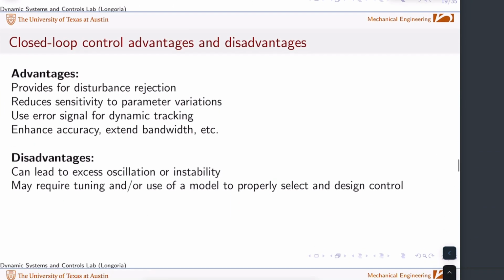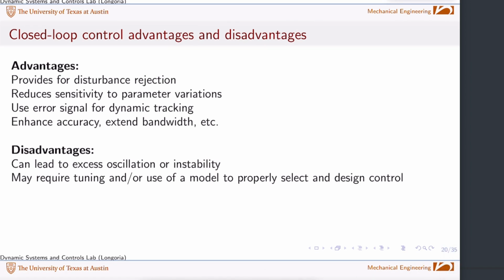It is good to discuss why we close the loop as opposed to open loop control, which was discussed in the first video. The advantage of closed loop control is that if you do have disturbances in your system, it is meant to reject those disturbances. It can try to keep your variable, the output from your plant that you're interested in controlling, or the control variable, it can keep it on track, even if you have some external disturbances that you haven't accounted for in your modeling and in your analysis.